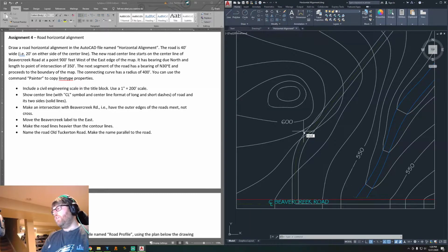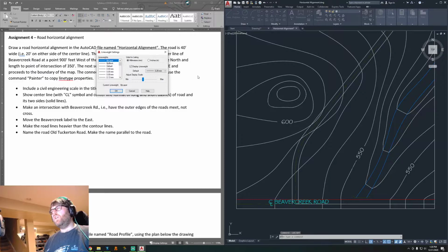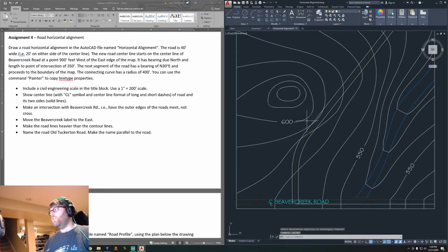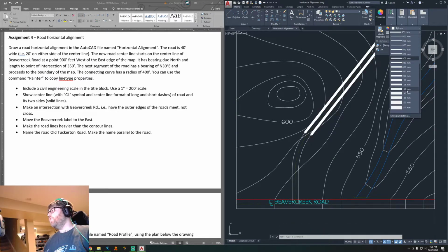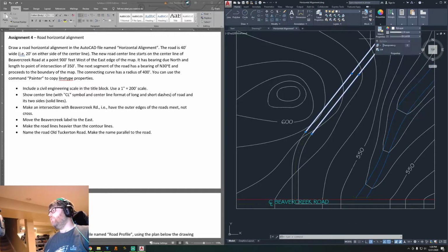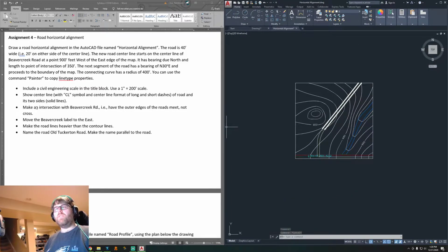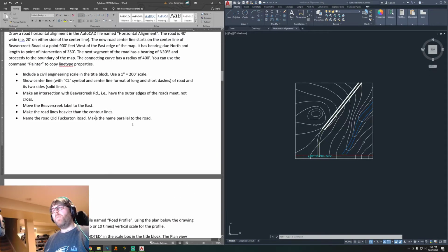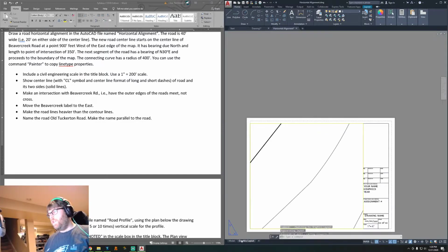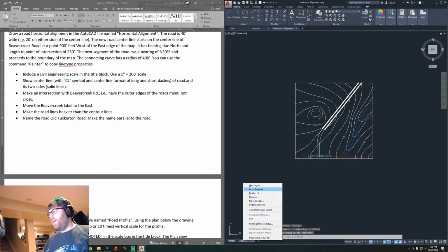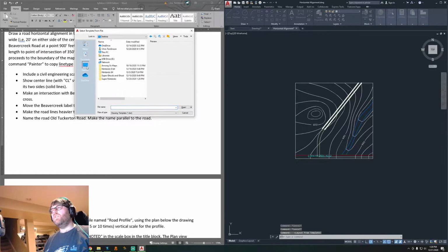So if we go to line weight, you could change line weights of things, or you could go into the thing itself, properties, and this one down here, you could make things thicker or thinner, however big you want to make it. But you'll do that for the entire thing. And then you'll end up putting it on the title block that I gave you. Don't use the one that's here. You'll want to add the one that